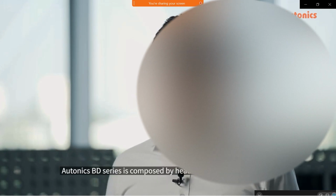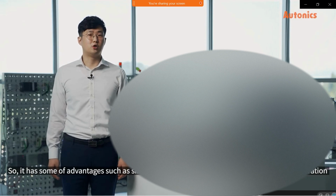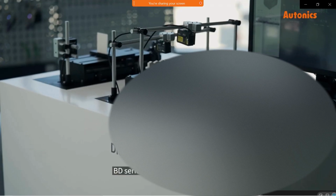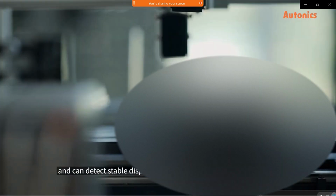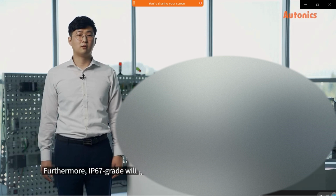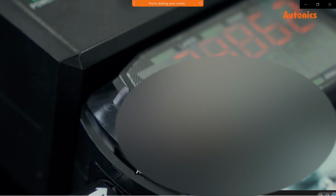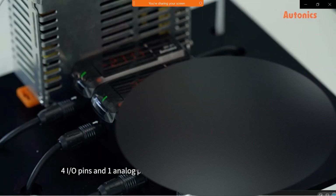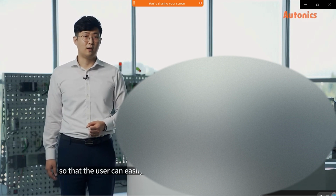Autonics BD series is composed of head and amplifier separately. So it has some advantages such as simple installation, easy maintenance, convenient operation, and real-time monitoring by the amplifier. BD series has up to 1 micrometer resolution and can detect stable displacement regardless of color or materials. Furthermore, IP67 grade will guarantee safe use in various environments. As you can see, 4 I/O pins and 1 analog pin provide some input and output settings so that the user can easily set the parameters PV, SV, RV, and bank.